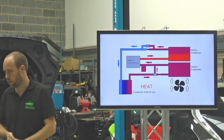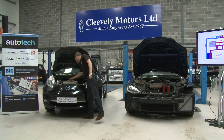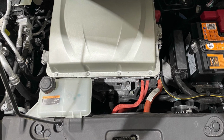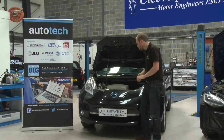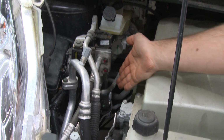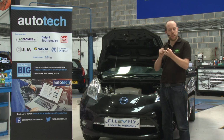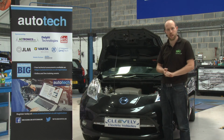So I'll show you the components on the Leaf. As I say, the cooling system is very basic on here. We've got our header tank, we've got our water pump, and the coolant just flows through all of the components and the radiator, and the pump just runs at the speed required for cooling. And then this is where we have our refrigerant valves. So you can see here is our three-way valve, here is our two-way valve, and these valves will change when the requirements change for cooling or heating the cabin.